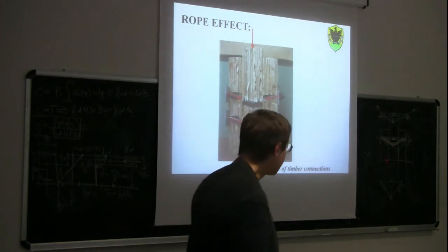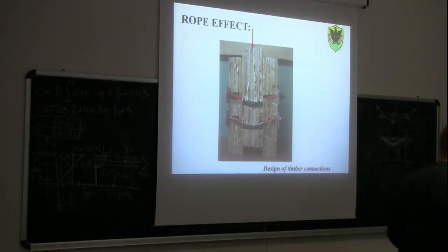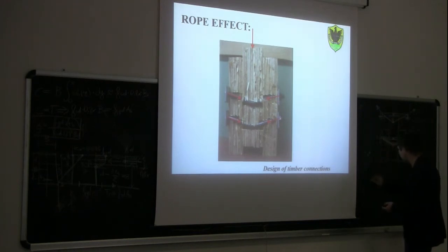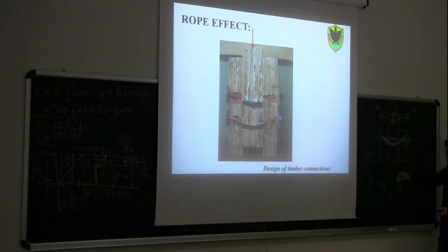So the plate provides this restraint, and for the principle that to each force you get the same reaction, the plate itself, if now I study the equilibrium of the plate, this is a tensile force, and the plate itself will have to distribute a number of compression forces at the interface with the wood itself.